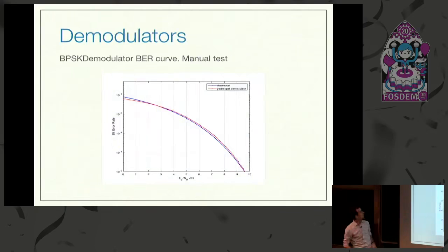All right. What can be improved? Demodulators. They definitely need to be improved. I haven't found any resources which clearly state what the standard parameters for demodulators are. So I have only the BER curve for the BPSK demodulator, and that's it. Maybe I need more parameters, like time to lock, time to relock the signal, and any other parameters. For the FSK demodulator, we need a BER curve or whatever. Multipath propagation is not covered here as well. So this is just an AWGN channel.